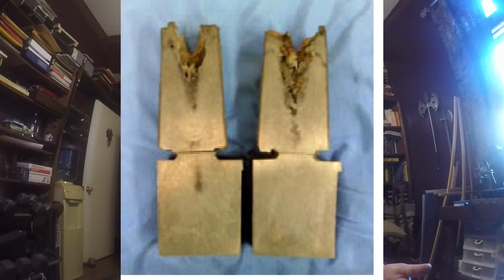You would fight all the rest of it because of that draft there. It wouldn't permit it. So once you take the top half, the cope, off of the drag, you'd be able to turn the cope over, wrap the blind risers, and pull the pattern for the blind risers out of the sand. So those have got to be blind risers feeding the casting down below, and they're just illustrating how much the risers actually fed the casting.